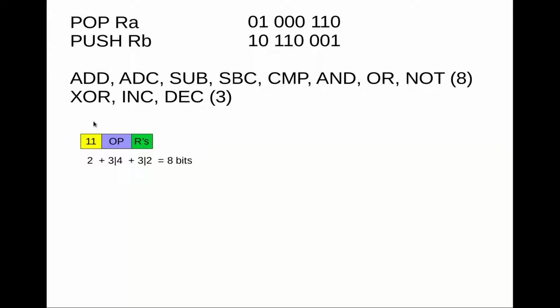We've run through it a few times. We basically point the memory at the value in the program counter, and then read whatever byte is there in program memory and write it directly into the instruction register. And we're going to use that in the control logic to determine what to do. And so if suddenly we need another byte to contain the actual instruction, well then we might have to increase the size of our instruction register, or we might need a second one, or we might need the control logic to start becoming stateful, because it would have to remember the decisions it made based on the first byte of the instruction, and then take further decisions based on the second byte. So it would make the control logic an awful lot more complex.